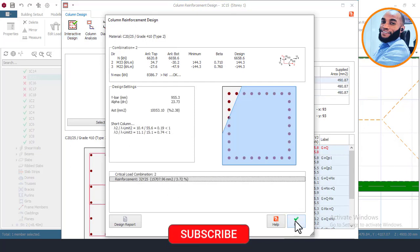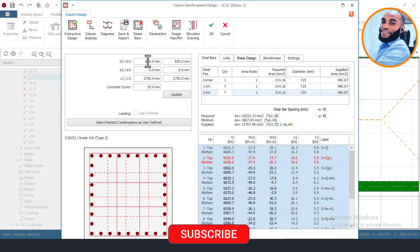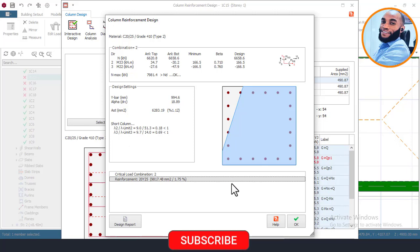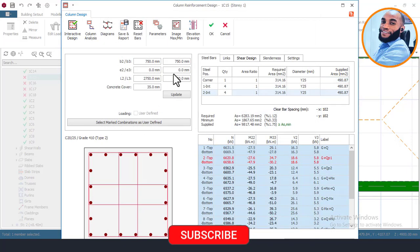I'll come here and then click okay, and then I can choose again to make it, let me say 700, or 750, just to maintain uniformity of my columns and to avoid too many groups of columns, I can choose to do that. So let me just choose 650 since that was okay, and then okay.